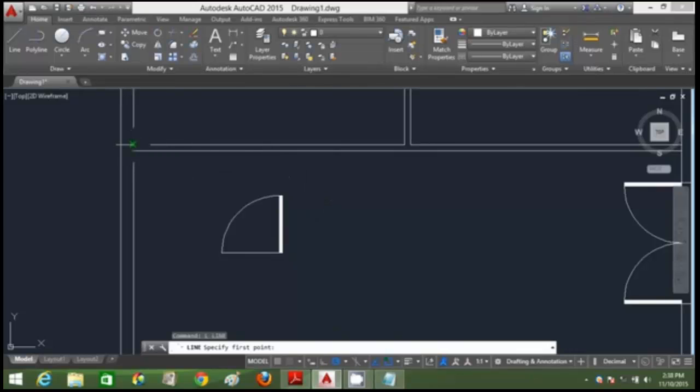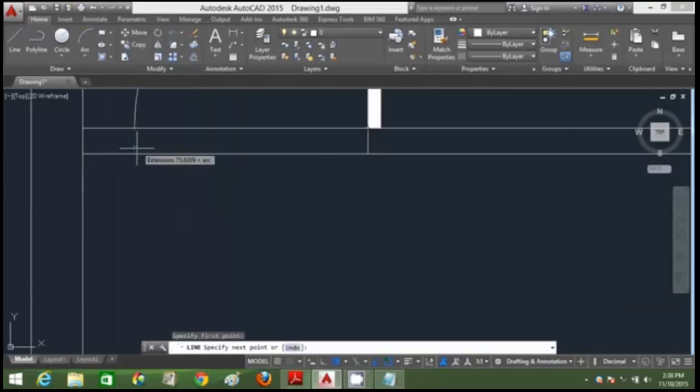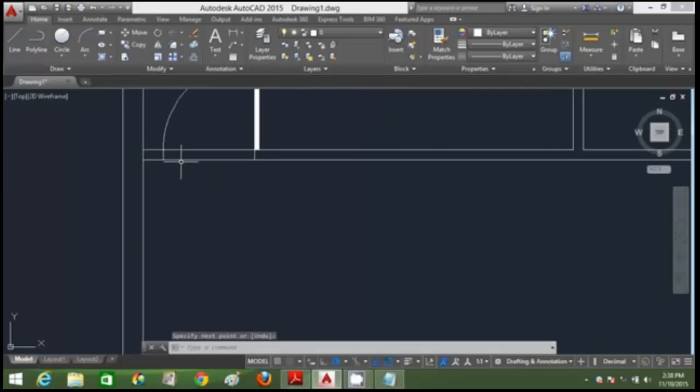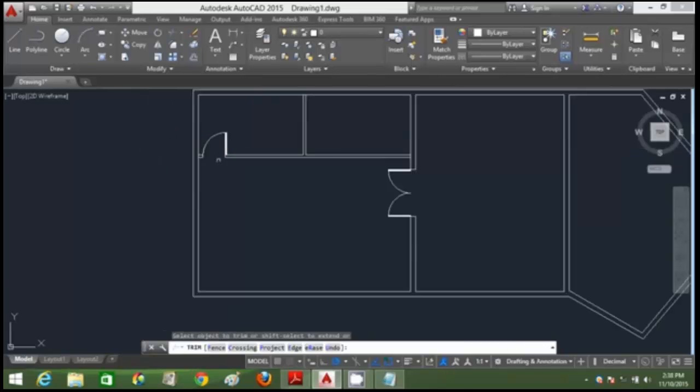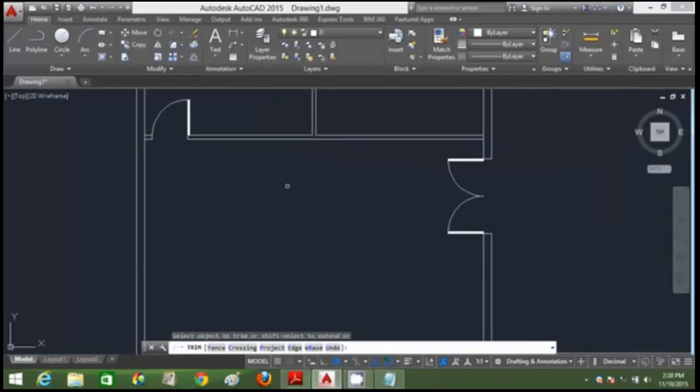I'm drawing a reference line here by 200 mm. I'm going to move this onto that particular reference line. I'm creating the boundary for the door. Click line, draw that line properly straight. Select the overlap line, delete it, trim out these portions. I have to delete the overlap line first before trimming it out.